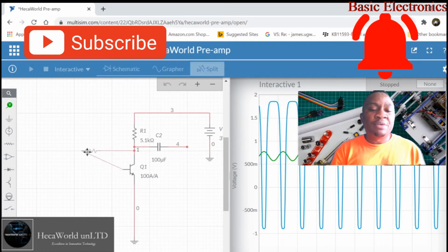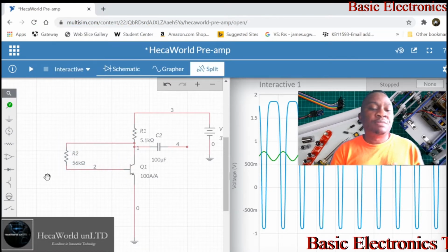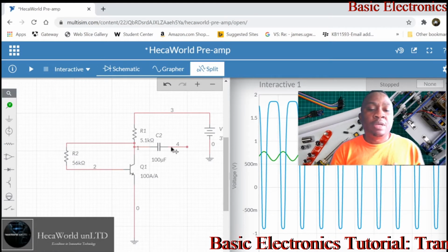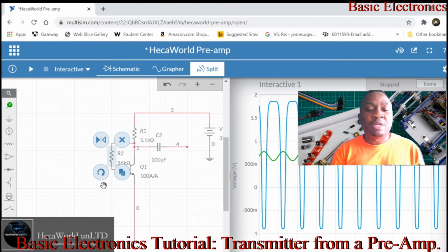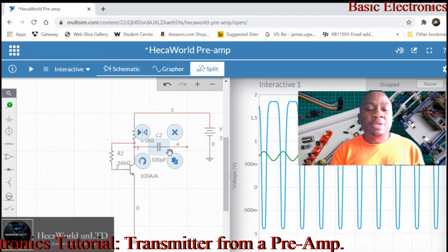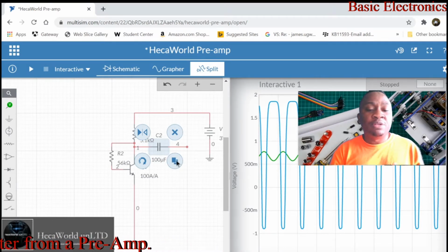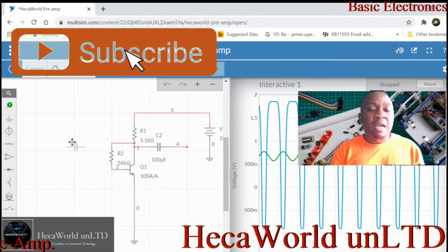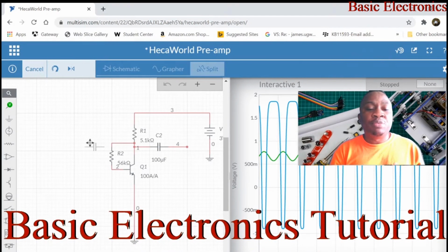So we're gonna rearrange this resistor. Same circuit we had before, and the capacitor, we can actually pull this in. There's no point putting it out there. Then this is where we're gonna do the magic, right? As a frequency determining network, we can put an inductor.